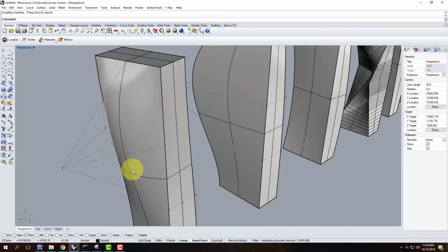So I have curvature in 2 directions. I have curvature going this way, and I also have curvature going this way. I can't flatten this out without splitting it in some way. There is a command in Rhino that will attempt to do it and split it out. I think it's called Splat. Anyway, I don't ever use it. It's kind of like trying to peel an orange. You can't take the peel off an orange in one piece. It doesn't work. So that's the problem.